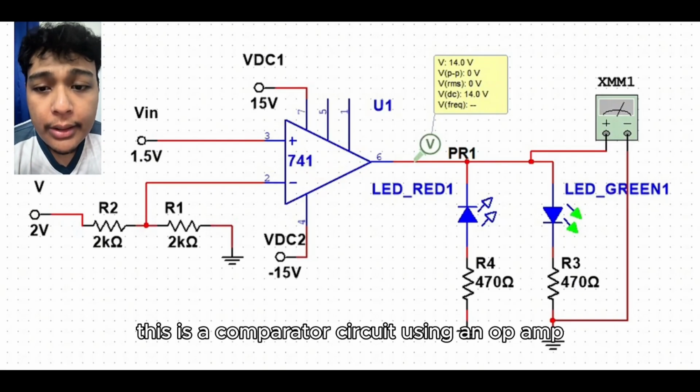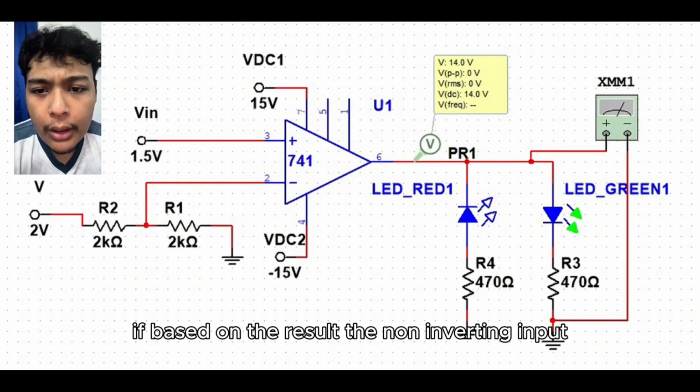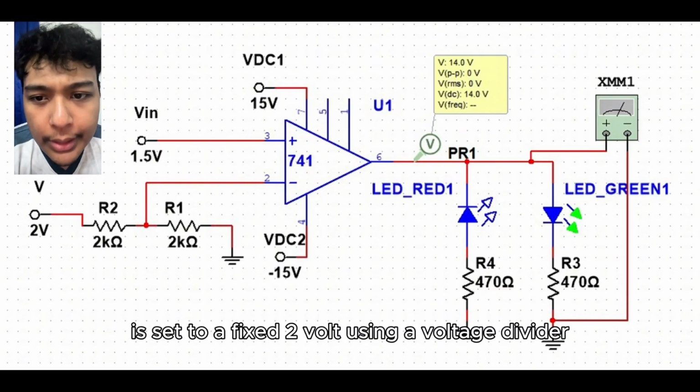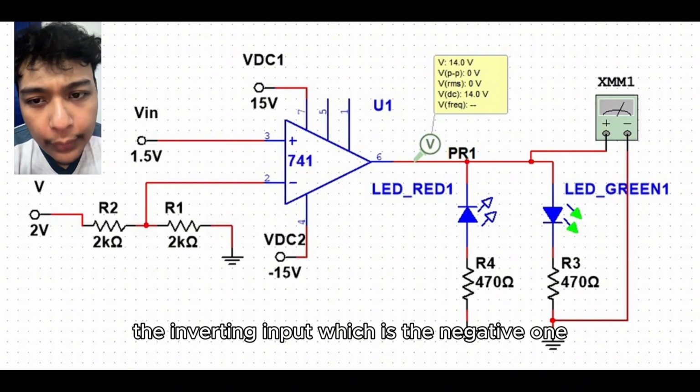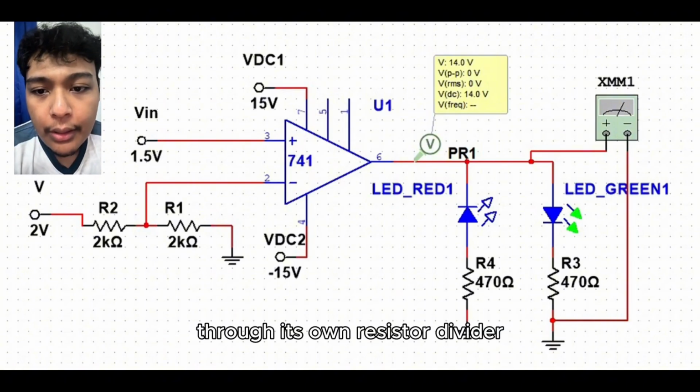This is a comparator circuit using an op-amp to compare two voltages and light up LEDs based on the result. The non-inverting input, which is the positive one, is set to a fixed 2 volts using a voltage divider. The inverting input, which is the negative one, receives the variable input voltage VI through its own resistor divider.